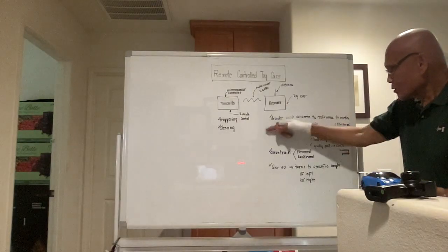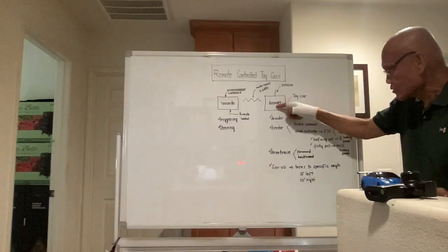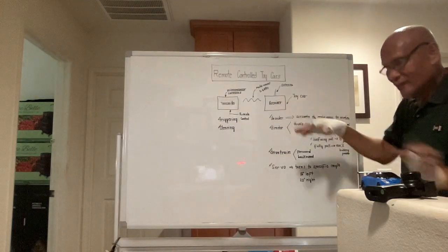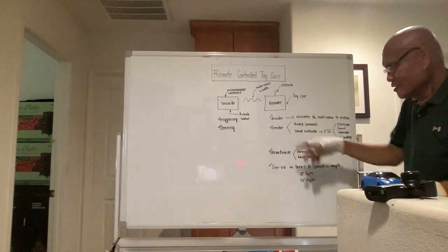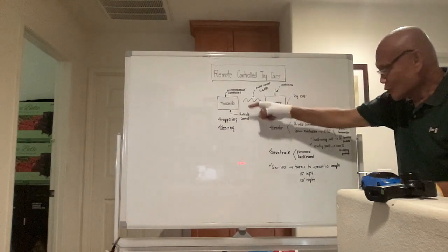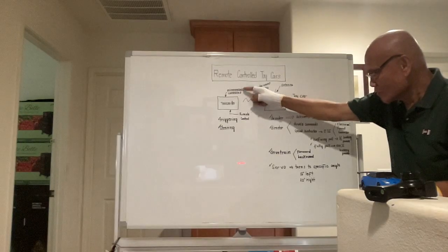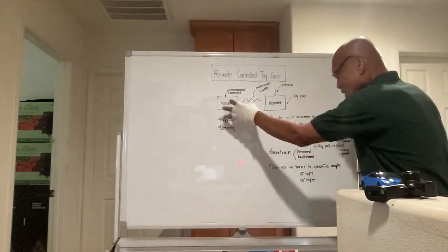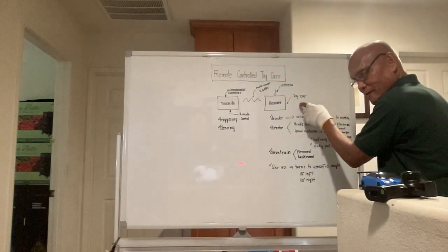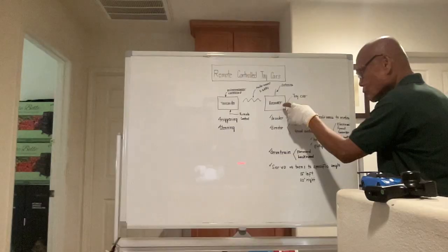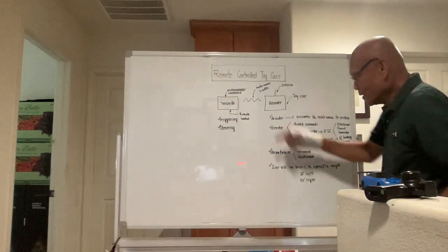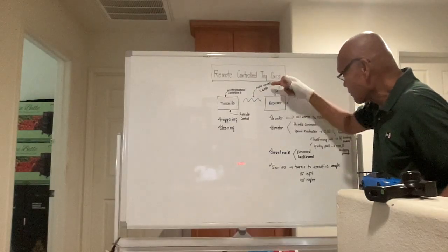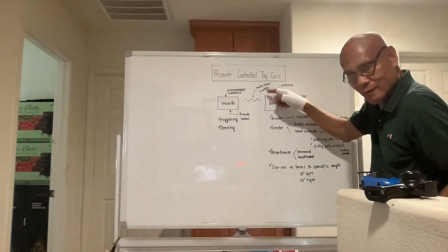The one analyzing all these things inside is the microprocessor on the receiver. So there is also a computer here. It's still a small microchip, same as the first one. This one has a microprocessor to activate the triggering and the steering if you want to operate this. And there's also a microprocessor for this one. So the first computer and the second computer talk to each other through radio waves, and the frequency is 2.4 gigahertz.